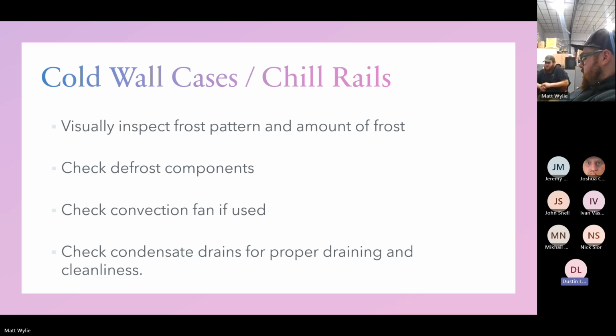So if you don't know what dryer it is, but you know your line size, or obviously the cubic volume, that's going to depend on the size of the system. I'm not smart enough to be an engineer and say it has to be this many cubic feet per inch or whatever. But if you ever need to know for sizing purposes, that last digit is a fraction of an eighth, and that will tell you your dryer size. As far as the cubic inches goes, I've heard it's always better to go bigger, never go smaller. You can match, but it's always good to go bigger.